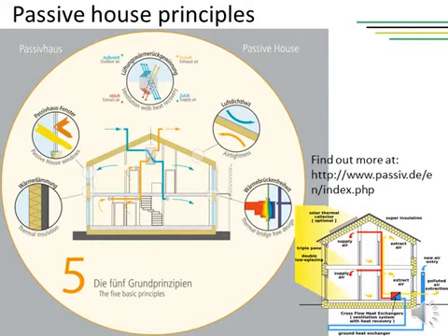Then it employs high-performance windows and doors. Typically so-called passive windows are triple paned with low-E glazing filled with argon or krypton to prevent heat transfer to outside space. It also uses a form of balanced heat and moisture recovery ventilation and uses a minimal space conditioning system. At least 75% of heat from the exhaust air is transferred to fresh air by means of a heat exchanger. This usually means using other types of renewable energy sources.